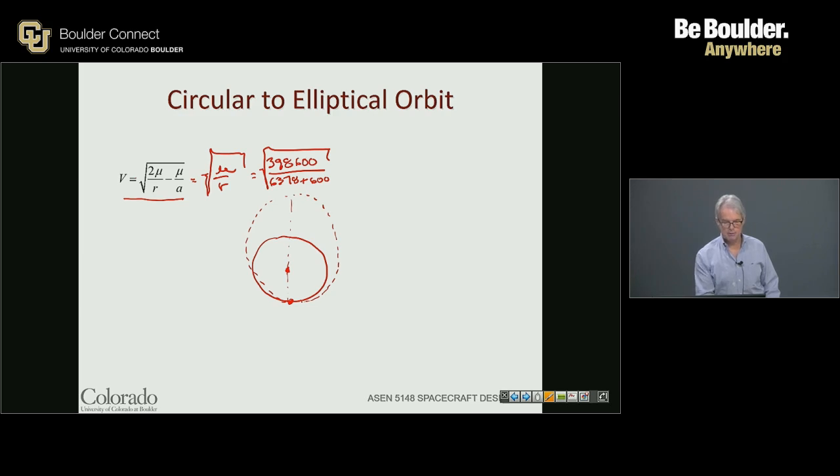And then I would come up with, let's say, velocity. I have velocity on the circle. I have now velocity on the ellipse, even though the spacecraft is in the same place. The velocity difference required is just the difference between these two values. So if I could fire an instantaneous rocket and change the velocity at this point with this kind of velocity change, then I'm able to go out on an elliptical path.